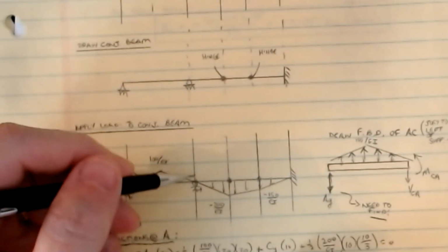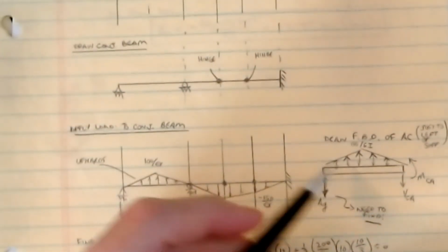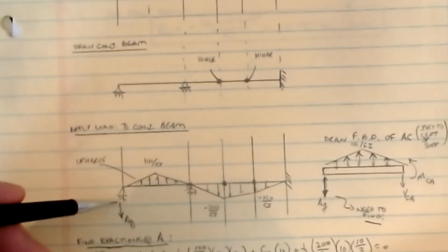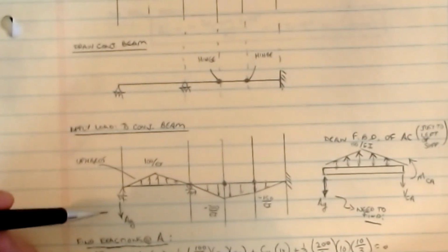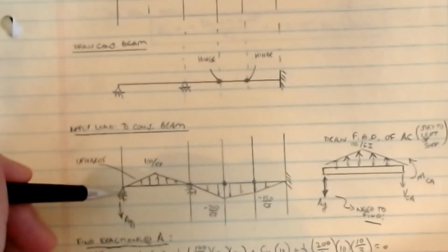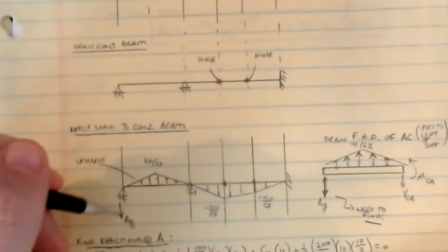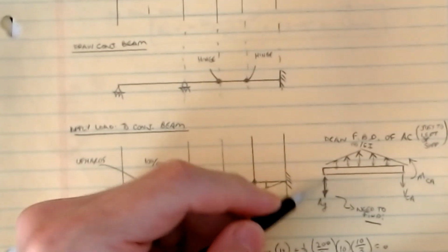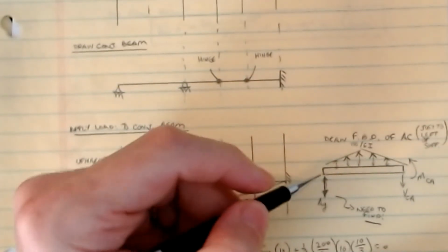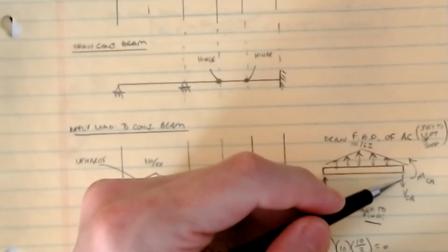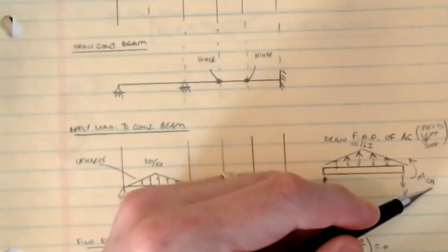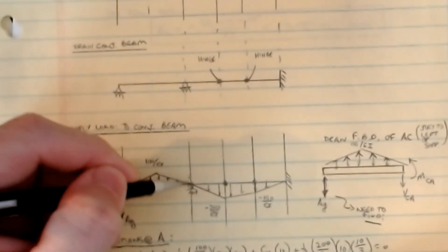So I'm going to cut it just over the support at C, and that's what I've done here. You've got your reaction AY, which I drew downward. I guess it doesn't really matter, so I assume downward positive. It's a little unusual for me to do that, but it can be whatever it wants to be. We don't know the value. We still need to find it. The structure you're going to solve then has a free body diagram that looks like this, with the moment at C on member AC. So that's why we've cut it here.